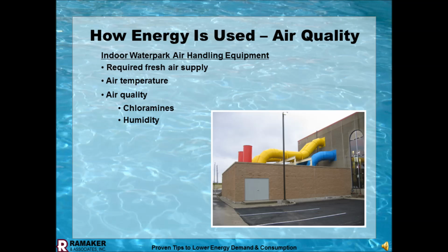And again, this is evolving. I've been involved myself for 13 years doing this work and seeing how it's working out. Before, we were taking 100% fresh air in, and that's taking a sledgehammer approach to it. The air handling units were that large to get that 100% fresh air in. You have flames to heat the air.